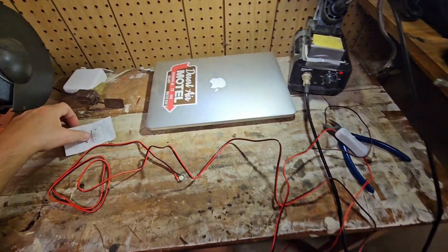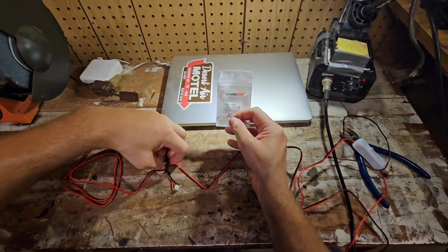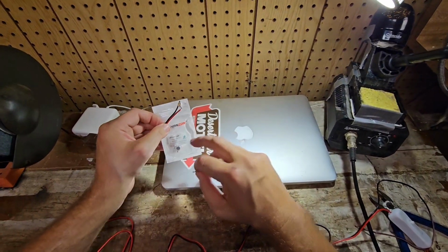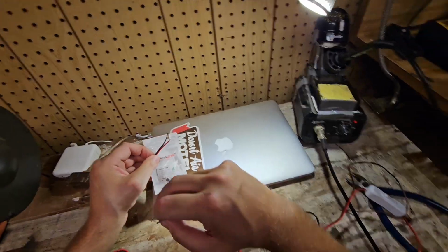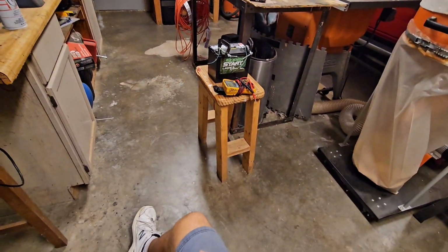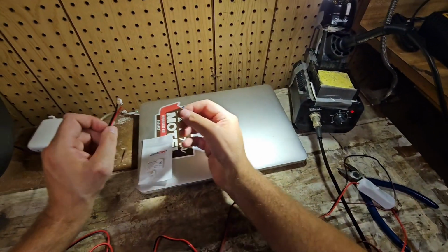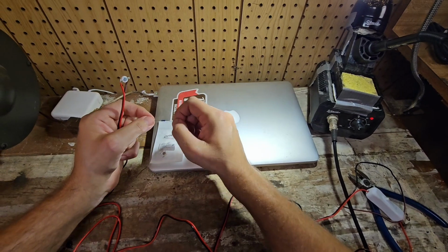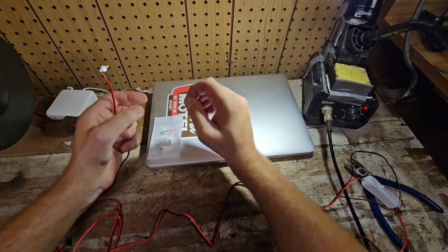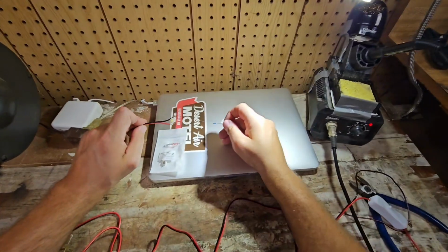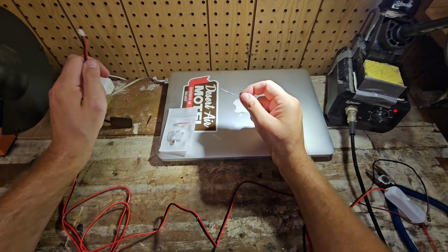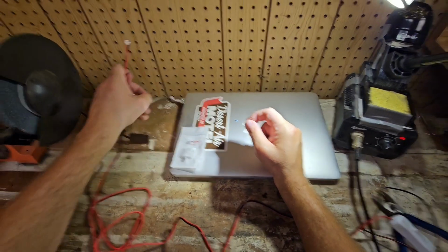Alright, there are things to note here. One, these LEDs we wired in are not rated to take the whole 12 volt load we're going to hook up to it. So we're going to wire a resistor in series with it, and that will allow it to work normally.